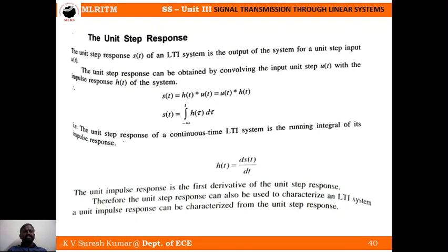Okay, so unit step response. Step response is denoted by s of t. We all know that step response means the input should be u of t. So h of t convolved with u of t is nothing but the step response. You can reverse it, u of t convolved with h of t, and the answer will be s of t equals the integral from minus infinity to infinity of h of tau d tau, because u of t minus tau will be 1 within the limits.